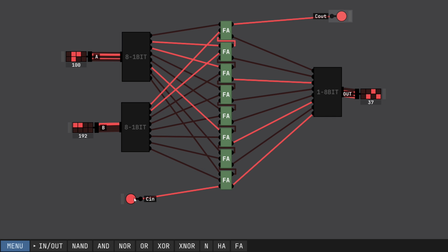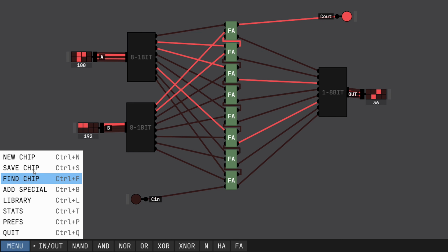Because we're carrying in an input, these two are closely related, which again will allow us to add numbers that are more than 8 bits on an 8-bit computer, which is exactly how an Arduino works. So an Arduino is an 8-bit computer, but it can add numbers that are greater than 8 bits thanks to this little carry out sequence in computers. And that's how early computers also worked too. But this is essentially our full 8-bit adder.